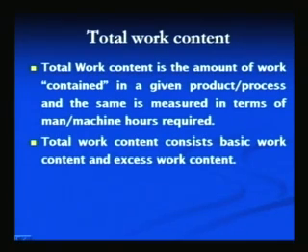Due to the various inefficiencies of the system or the product design, this excess work content is observed, and that is required to be done. So, if we have to reduce the total work content, then the excess work content is targeted, because basic work content is the minimum required work to complete a given job or operation. These two, the basic work content and the excess work content, have to be understood very clearly for attacking the excess work content and making strategies for increasing productivity.